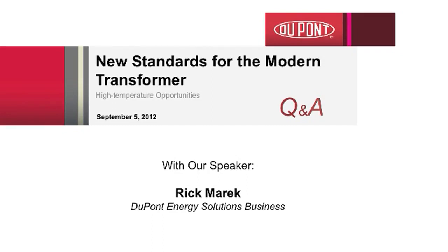Is water a byproduct of Nomex insulation aging in the same way and degree as it's a byproduct of Kraft paper-based insulation systems? Well, there's good news and bad news. The maybe good news is that no, water is not a byproduct of Nomex as it degrades, but on the other hand, we have not found a tracer either. So I would have to say no.